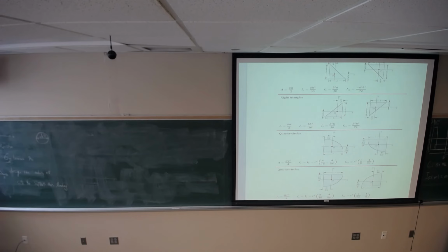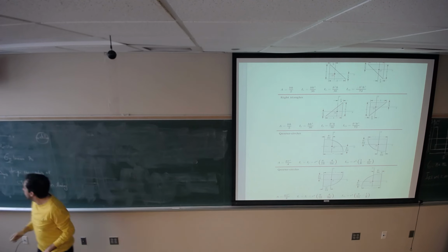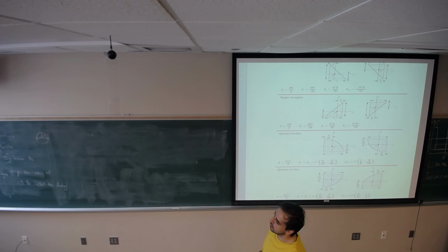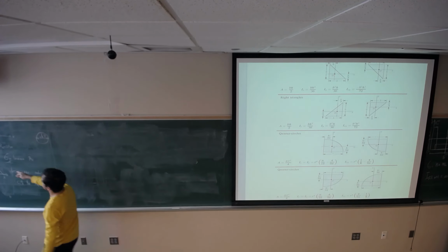And then draw the bending moment diagram. The bending moment diagram is going to look like this. By looking at this, you will notice that if this is point A, B, C, and D, section B is going to have the maximum bending moment. The value is 1,800 pound-inch. So the critical section is located at point B, which is 6 inch from point A, and the magnitude of the moment is 1,800.